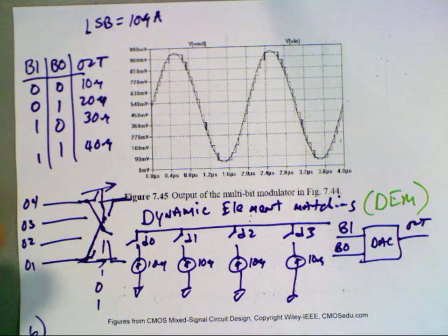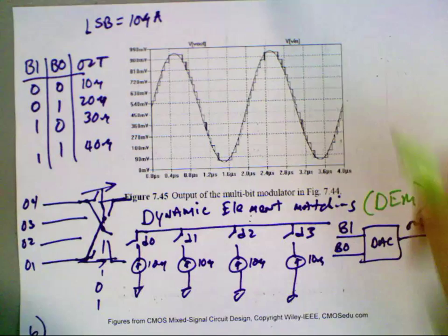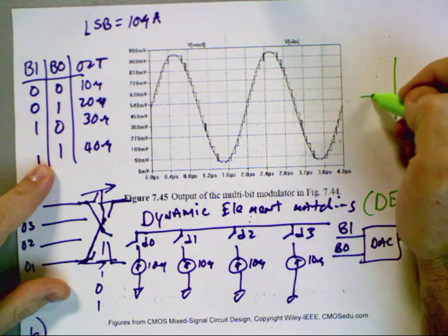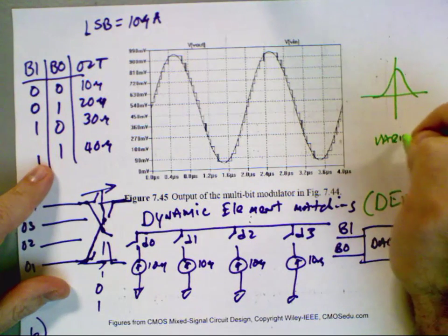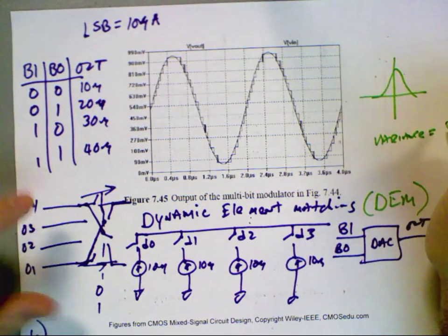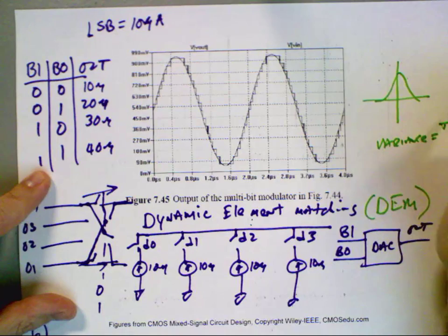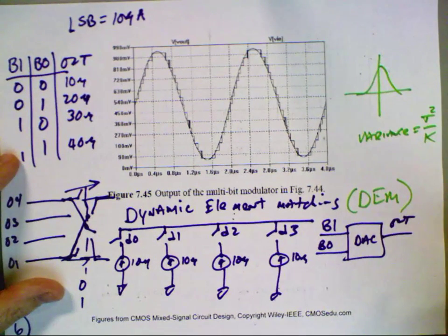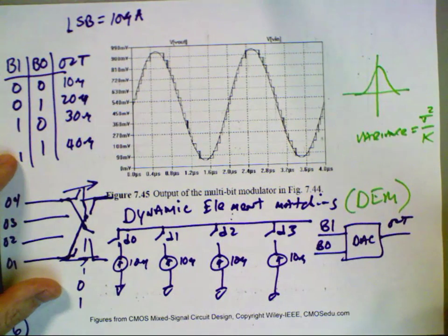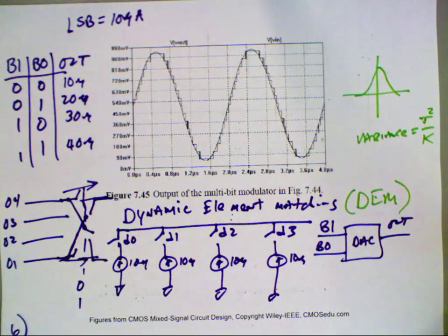So I'm saying nothing more than when I looked at the quantization noise in time, if it has a Gaussian distribution, then the variance, whatever it is, sigma squared we'll call it, is reduced by the number of points I average. Or the standard deviation is reduced by the square root of k. I'm just repeating the same old thing. Any questions? Okay, I want to show one more example here, but it's just randomizing the feedback.